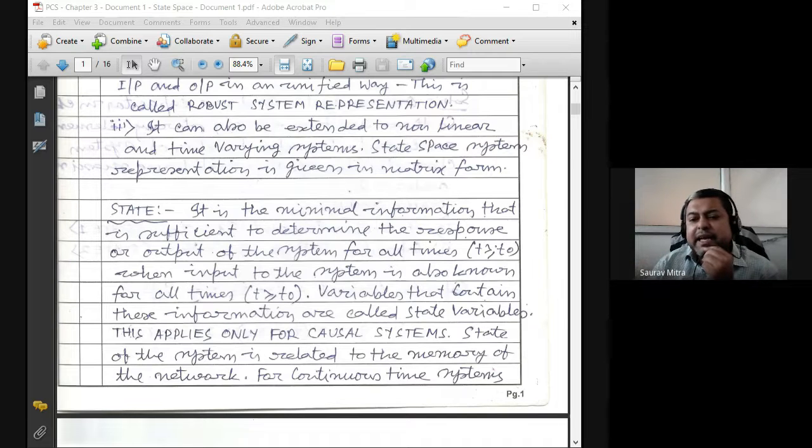All the components carry the same current, but we generally call it the inductive current, because whenever frequency is very high, XL is very high, so the circuit will behave like an inductor. That's why we call it IL. So IL can be one state of the RLC series circuit. What can be another state? VC, the capacitive voltage, can be another state of the RLC circuit.